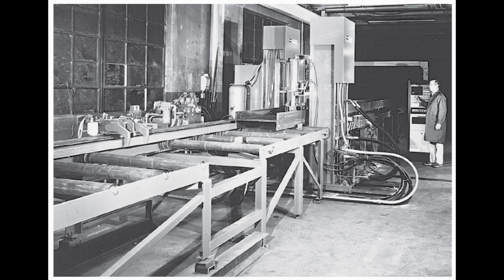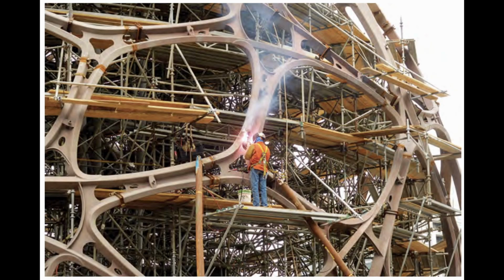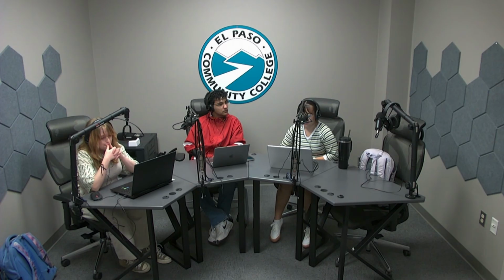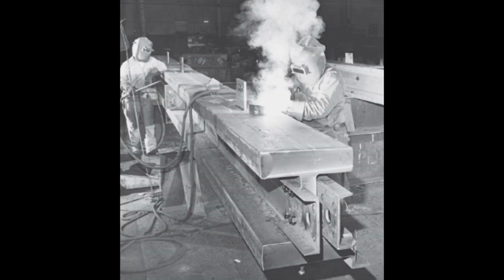The steel pieces are cut, drilled, and marked with templates in the shop. The steel pieces are also labeled with codes for proper placement in the building, and the beams and the girders are cambered, and the steel shapes can also be bent and fabricated into complex geometries. For stiffer plates and connecting parts, they are welded or bolted to the steel components. And lastly, they are assembled in units to be ready for transportation to the construction site.